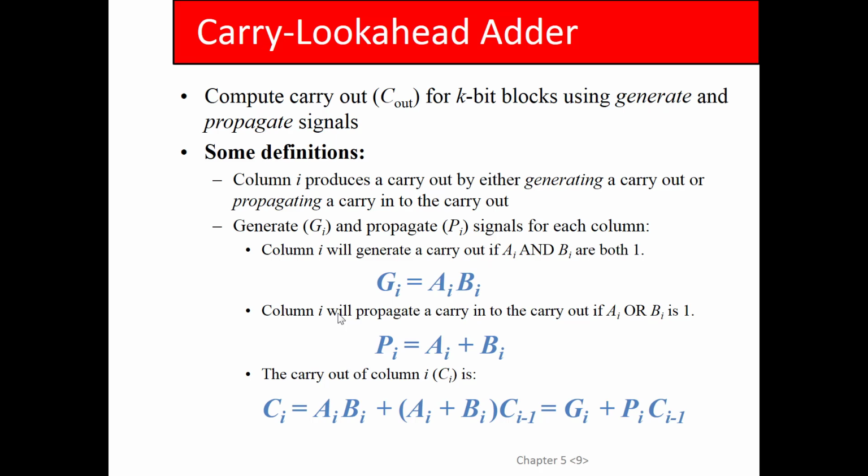And by the way, when I first saw this, I was like, wait a second, hold on. You said that we have a synthesizer, right? The whole idea was that if I give a truth table to the synthesizer, it will generate logic for me, right? In fact, the synthesizer can generate different versions of the logic where trade-offs are made between gates and delay, right? So why do we have to worry about this? Why not just build a truth table that performs the adder and give it to the synthesizer? Problem solved. It'll generate a customized circuit that does an add, right?